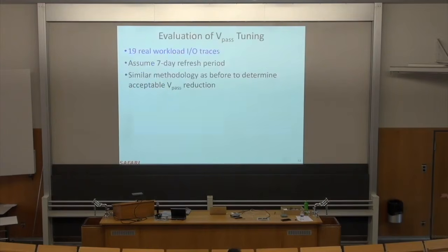And we evaluate this. You basically assume a 7-day refresh period. This works much better, of course, if you refresh your flash. If you don't refresh your flash for 3 years, then your unused ECC capability is very low. That's one other reason for refreshing your flash once in a while. That actually gets you better use out of your ECC in the end. So not refreshing the flash is not a good solution, because your ECC capability becomes much worse, since your retention errors accumulate and ECC is correcting those retention errors. Refresh is a much easier mechanism to correct for retention errors.